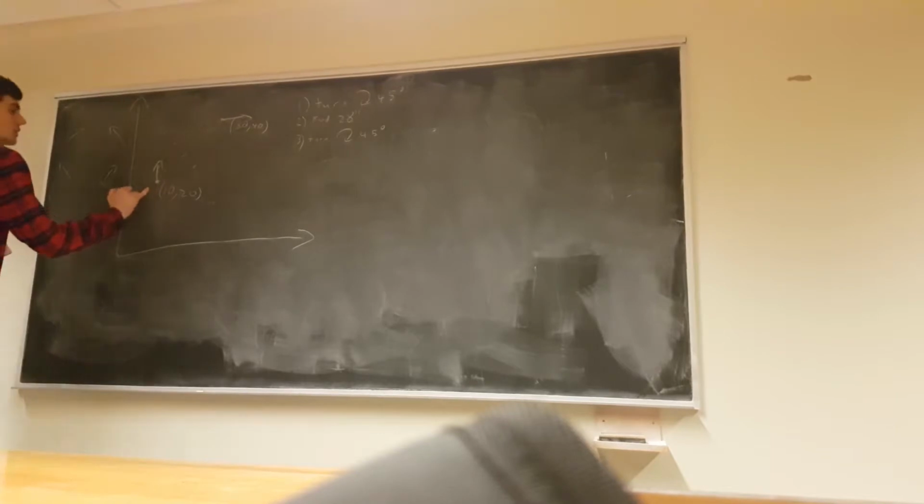Another one. We talked about only one particular type of error, which is just not going far enough, or maybe slightly overshooting, right? How do we know that the robot's going to turn around its center? Ideally, if all 4 motors spin at the exact same velocity, their velocity with respect to time curves look identical, yes, it will spin around the center and it will drive perfectly straight forward.